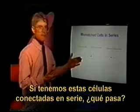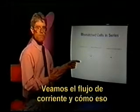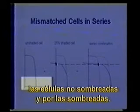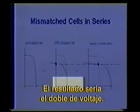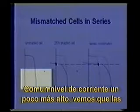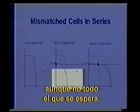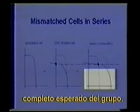If we have these cells connected in series, what happens? Let's look at current flow and see how that adds up to give us our composite IV curve. At a low level of current, we would have voltage contributed by the unshaded cell or cells and voltage contributed by the shaded cell. The result would be double that voltage. At a slightly higher current level, we can see that the unshaded cells contribute voltage. The shaded cell contributes some, not quite all the voltage we'd expect from it, but some voltage. So the composite result is almost the full voltage we'd expect from the group.